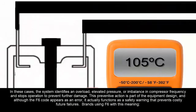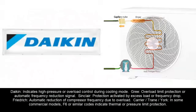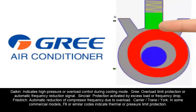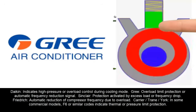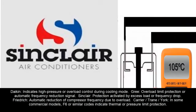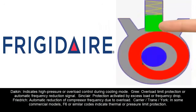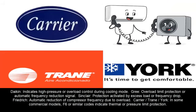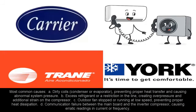Brands using F6 with this meaning. Daikin indicates high pressure or overload control during cooling mode. GREE, overload limit protection or automatic frequency reduction signal. Sinclair, protection activated by excess load or frequency drop. Carrier, Trane, York. In some commercial models, F6 or similar codes indicate thermal or pressure limit protection.